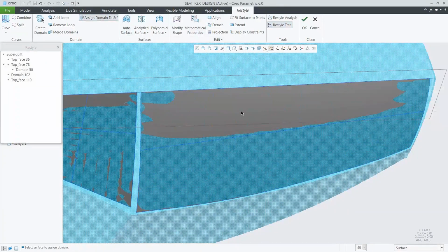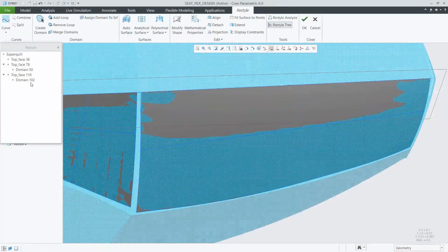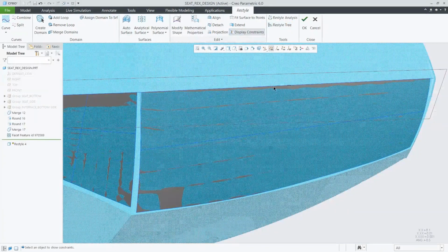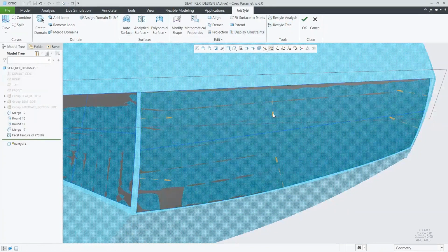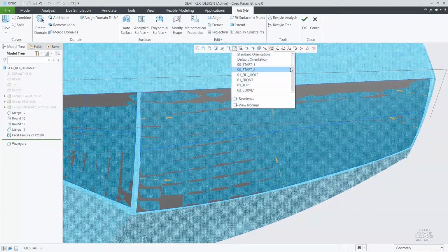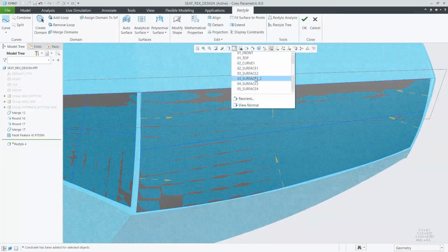And it's not the typical Creo workflow that you would normally see with the parent-child relationship. It's using that facet geometry to create the domains, the curves, the surfaces, but once they're built, you're really free to work with them however you want. You can change around that geometry without affecting anything else up the line.